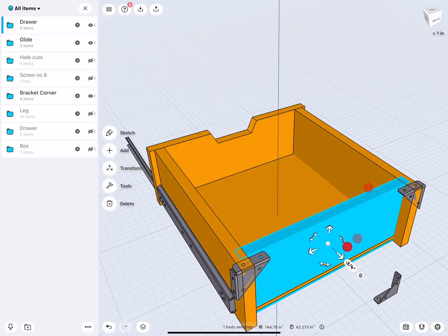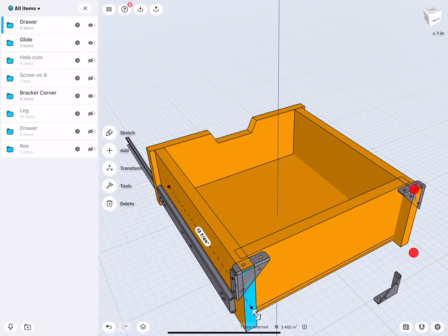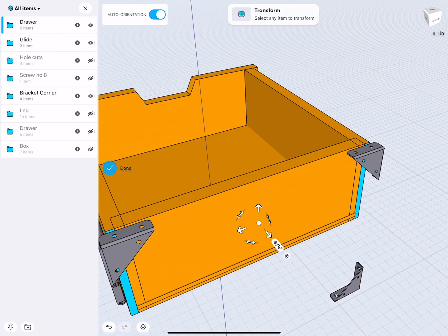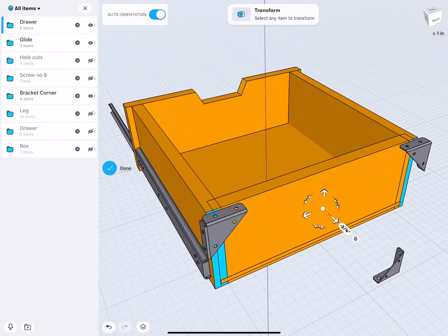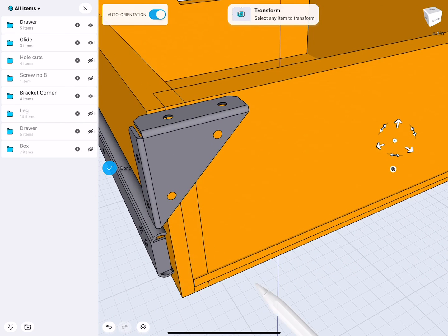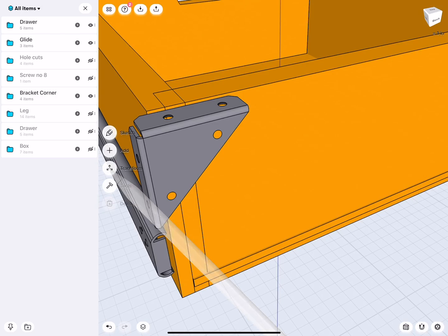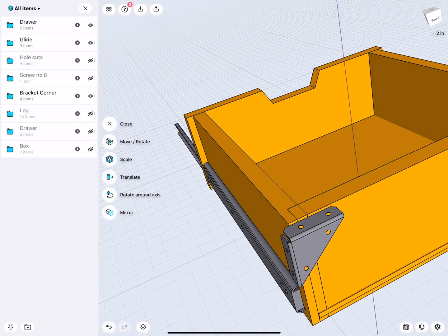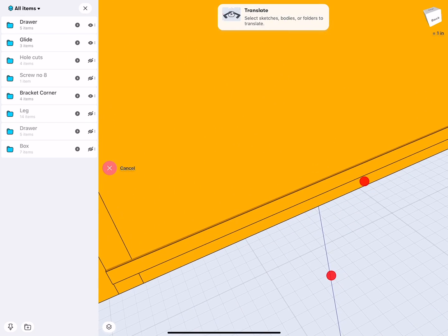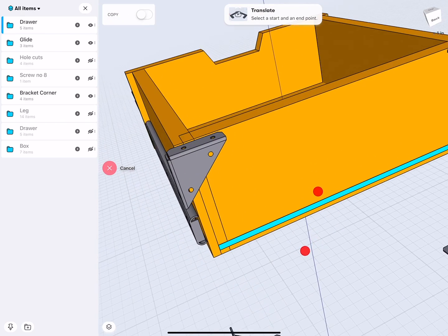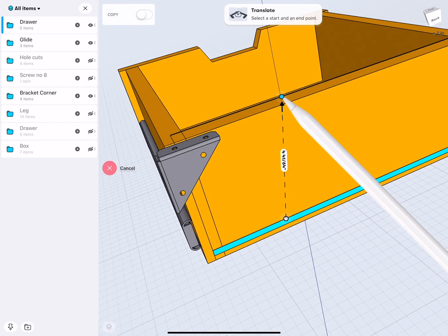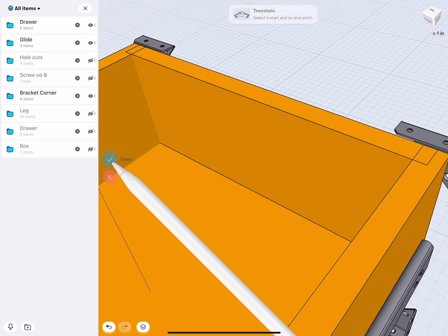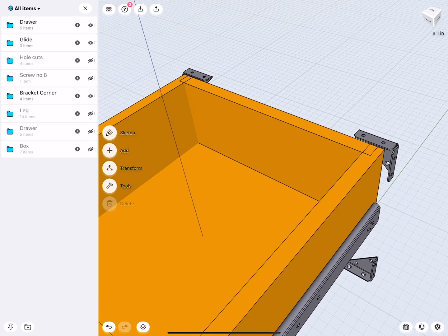So that means also then this and this face I need to move back 3/8. Very good. This face I would like to line up with this face. How do we do this? The translate tool is amazing for that. So I select this face. Good. So then you snap to there. So I snap this corner to that corner. Done. Zip. There you see it got adjusted.